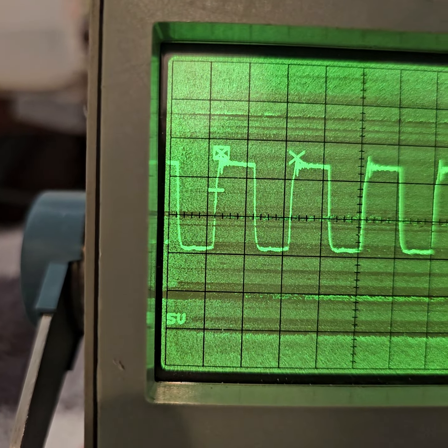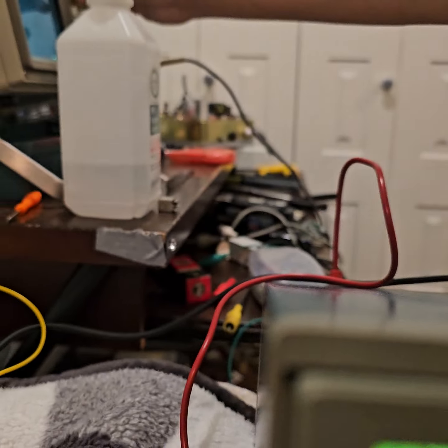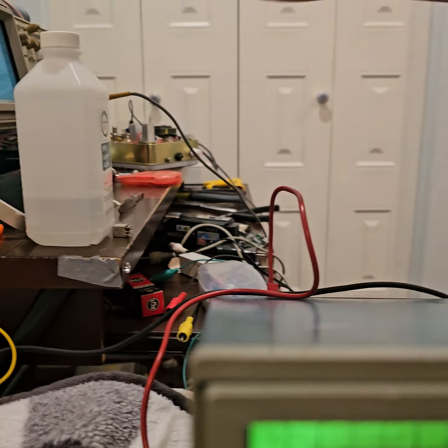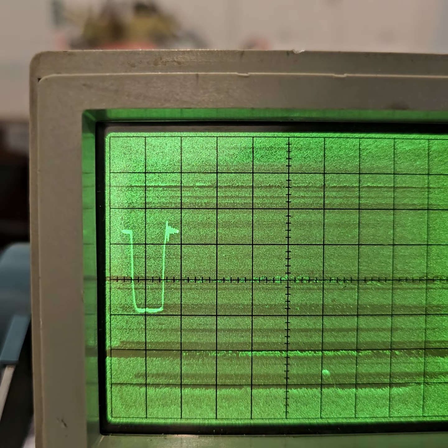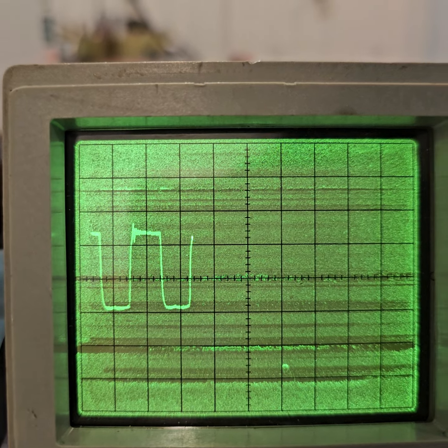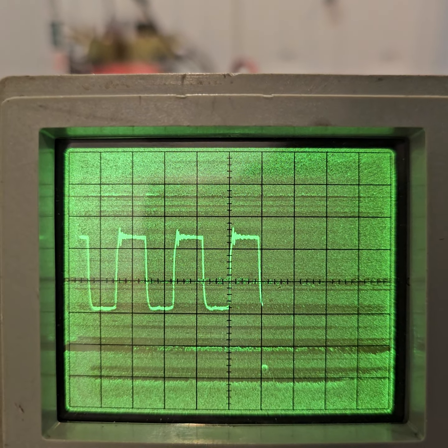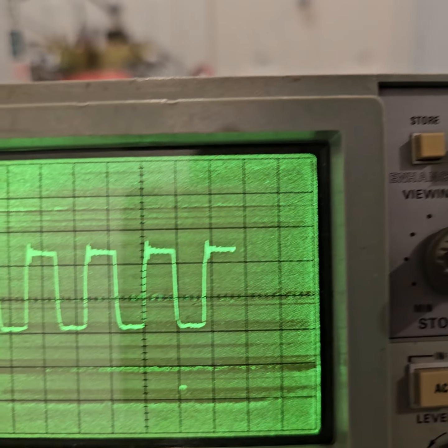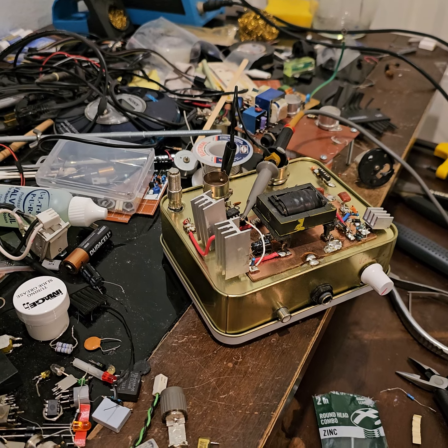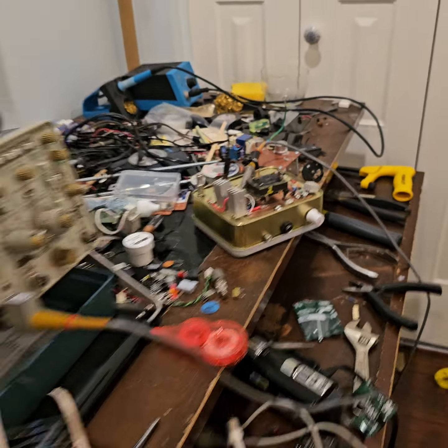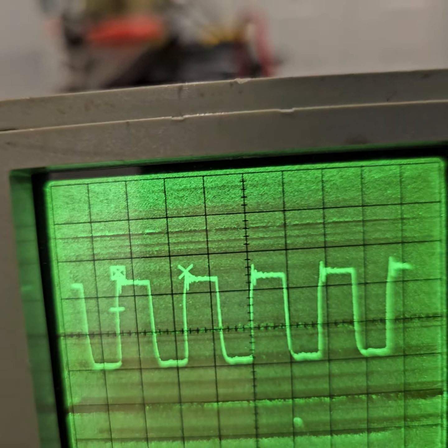It's writing out the multiple division. Oh, I need to erase this. I put the gain too high. I have to restart. There we go. I put the gain a little bit too low this time, but it should get the whole thing in, I guess. There's our square wave. This square wave was taken from this sort of switch mode chopper supply. There's a lot of ringing in there, and you can see the ringing at the rising edges of the waveform.